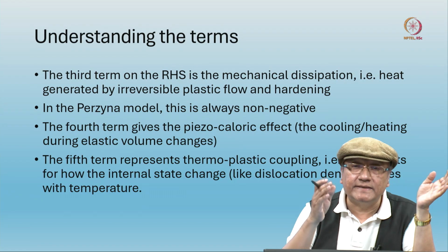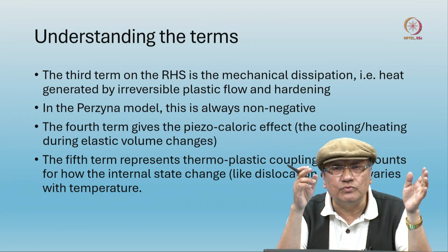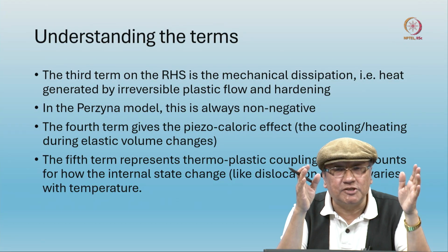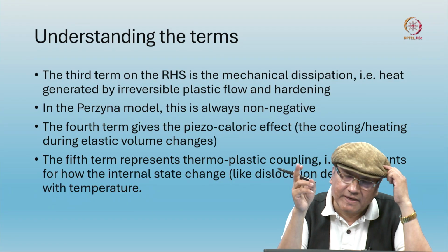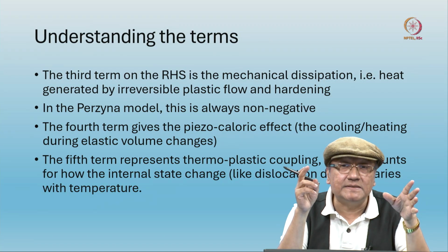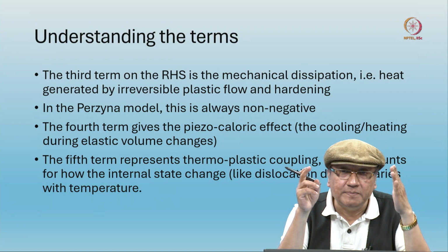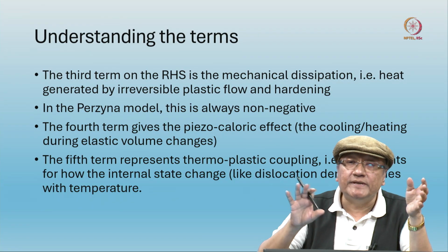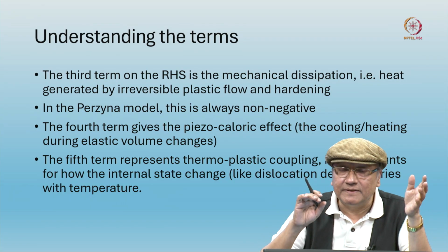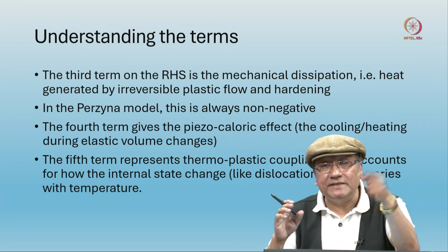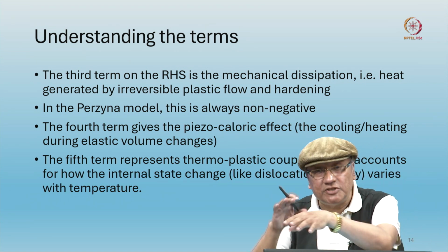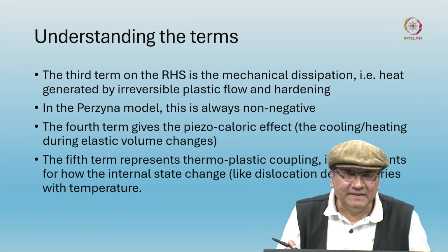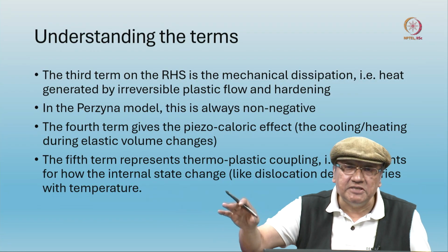The full of this dissipation need not go to temperature rise, because some of the heat that will be generated will be used to drive the microscopic changes in the microstructure. That will not come as temperature, because part of the heat energy is going into changing the microstructure. So, that is already spent in changing the microstructure.